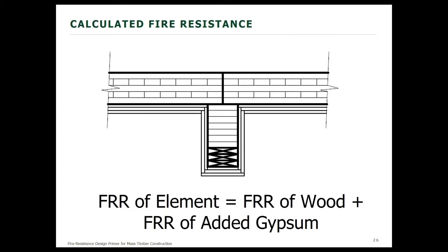What I'm showing here is a graphic showing the fire resistance rating achieved by adding the fire resistance rating of gypsum wallboard to the fire resistance rating of properly sized exposed wood members.